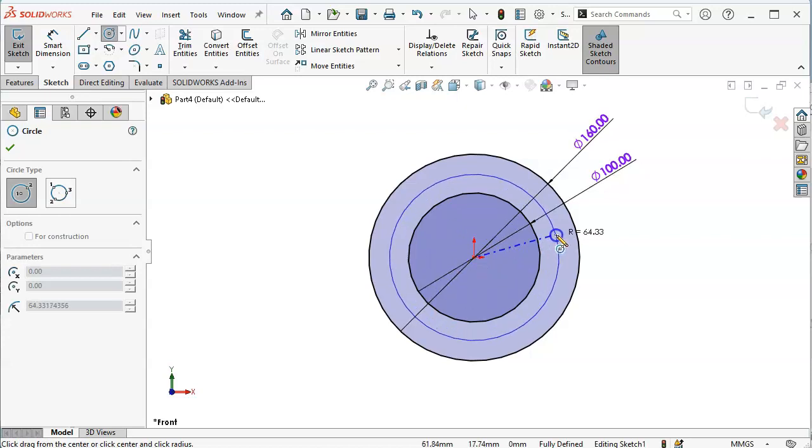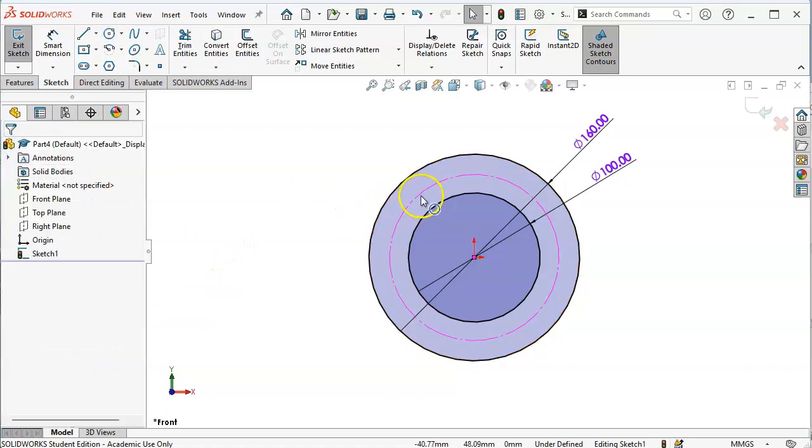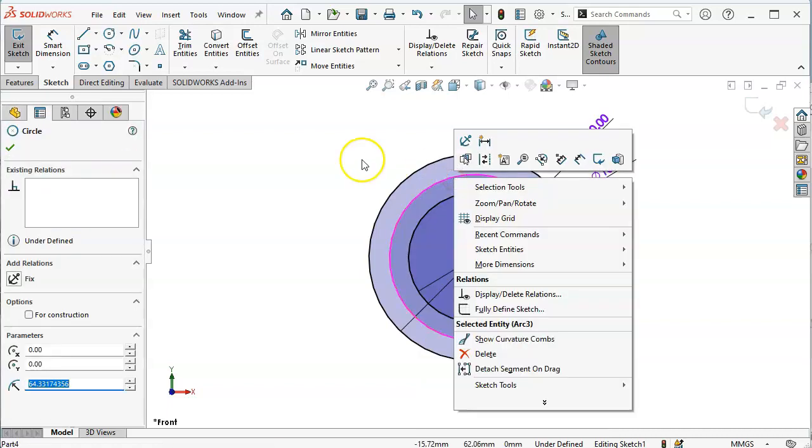All right, where it gets a little weird is I really like to have that base circle for any of the circular patterns, but there is not a tool for creating a center line or a construction line circle. We have to draw the circle and then check on it to do for construction. The other item of interest is on the context menu. The second row, second item in is the construction geometry. So that'll toggle between objects.